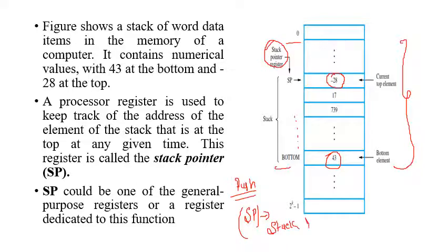This stack pointer holds the address of the stack. So it is not constant, it will never be constant. When you push the data, there are two possible ways. Either you may push data of word length 32, you can push of word length 16, or of byte. Based on the word length, the stack pointer will hold different types of address. For example, if it is a word length, let me assume this bottom address as 0x200.